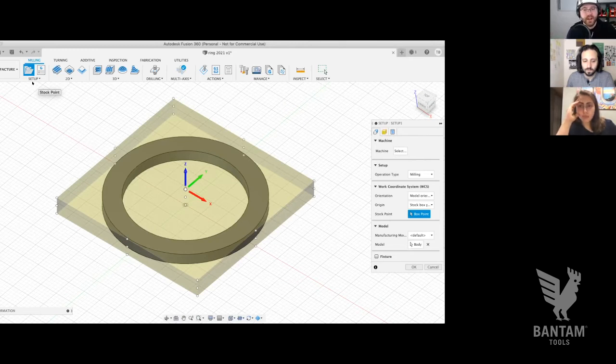And then we've got this other thing on there, Z, Y, and X. That's in reference to the mill itself. It's your work coordinate system, where Z is the up, in this case, for our purposes, Z is up and down, Y is forward and back, and X will be left to right. That coincides with parts on the mill that we're going to be moving. We can move the bed on the mill, which is what's going to move the stock forward and back inside the mill. That's on the Y plane.